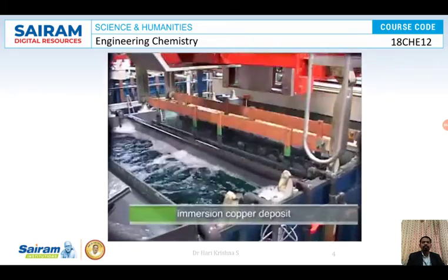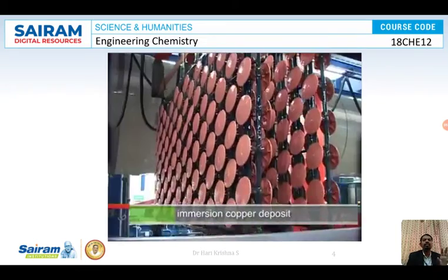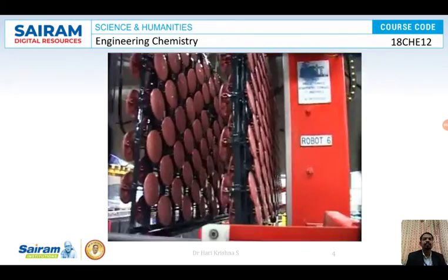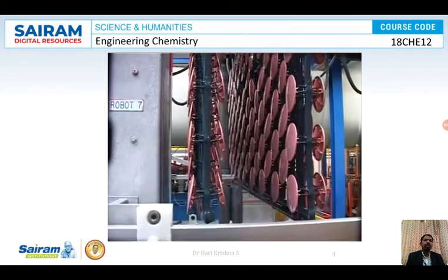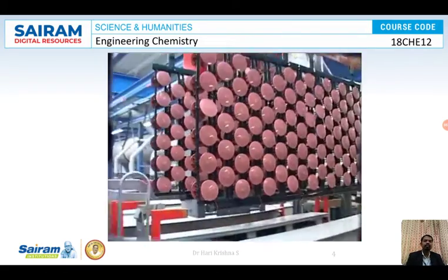After creating the initial conductive layer with the electroless nickel, racks of parts are processed through an immersion copper solution to further improve their conductivity. There are no anodes here. So it looks like copper is plated here. It is deposited over here.